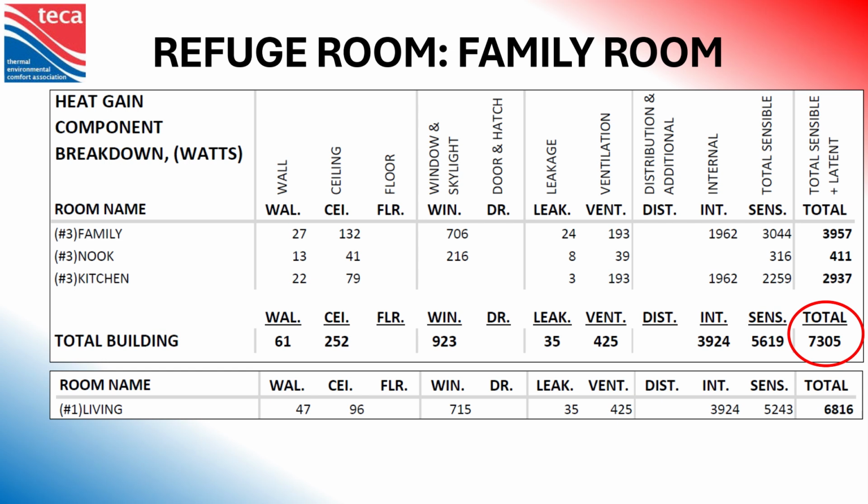So really what I'm getting at here is leakage is the same, ventilation is the same, interior loading is the same, and that's the majority of the load. So we can move that same unit to the kitchen, family room, and breakfast nook and provide a whole lot more thermal comfort. Same equipment.